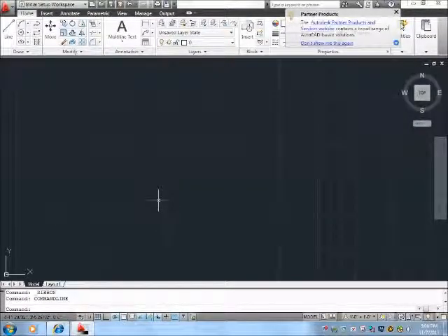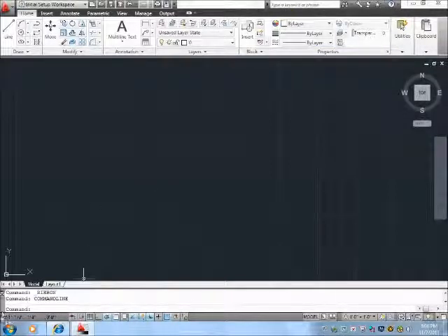And now that we're in our initial setup workspace for working on our Georgian house, you should notice if you come down here that the units have changed. They've changed from being just basic numbers to now they should say 1 feet, 2 feet, 5 feet, and inches. So you'll have your feet and inches now laid out. It'll make the process of working on the house design a whole lot easier, since we can now put in specific units of measurement instead of just putting in numbers.